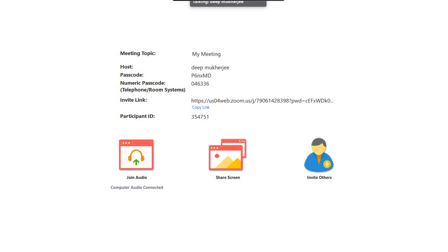You have noted that equation, C1 and C2, epsilon 1, epsilon 2, E1, E2? Yes or no? Yes. Okay, then fine. I will also share, no issue. But if you have noted it, please try to calculate the net output voltage, what I said: that is E1 minus E2, and check the relationship between the net output voltage and the displacement. That is a very important setup, an important topic, the differential arrangement. I will show you one numerical example on capacitive transducers, and I will give 2-3 numericals also that you can practice.